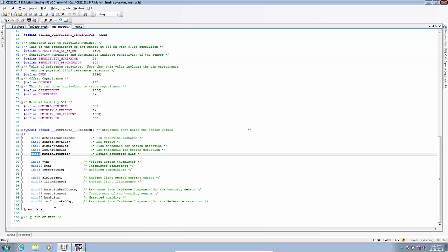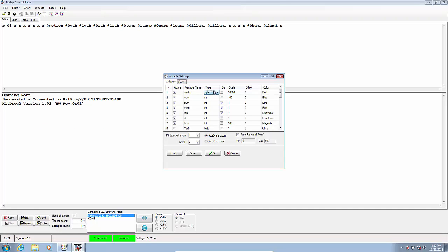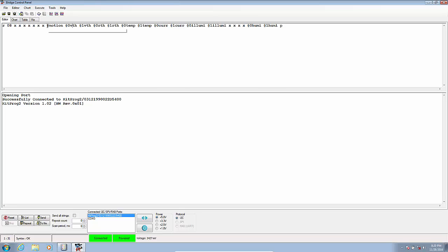For example, this is the unsigned integer 8, 1 byte, so no sign bit here. Then you can use the at motion, and it will copy the data when it performs a read operation. For example, if I click the send command, it's returning yes, 08, acknowledge, 03, 04, and you can see that this comes out to be 00, which means motion has not been detected.